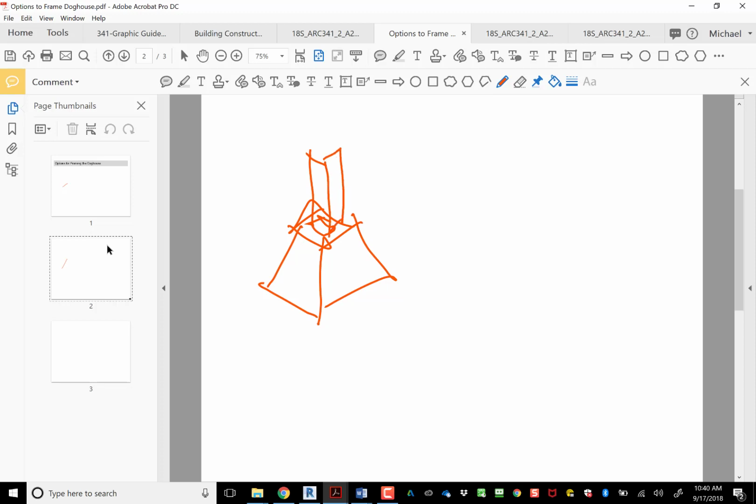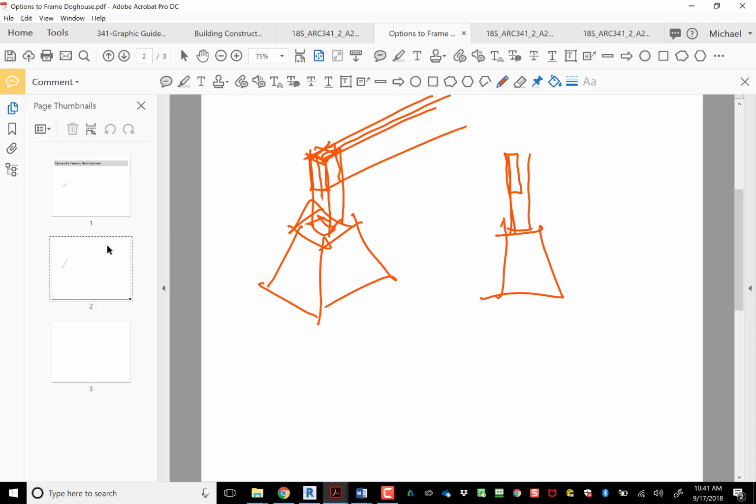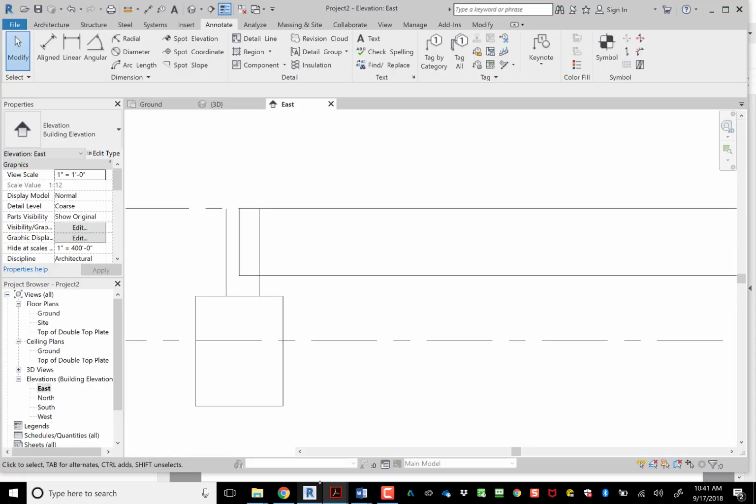So, sorry, that's the flanges. You could put a 4x6 in here, which would be huge and heavy and expensive, okay? Or you could put in a 2x6 like this, and then just shim it with another piece. So in section, you have your flanges here, and you put your rim joist here, and then you would put a piece of blocking there, just so that it doesn't collapse on itself. Okay, so that's option 2, and there are other options as well. Okay, so sorry, we'll keep going here.